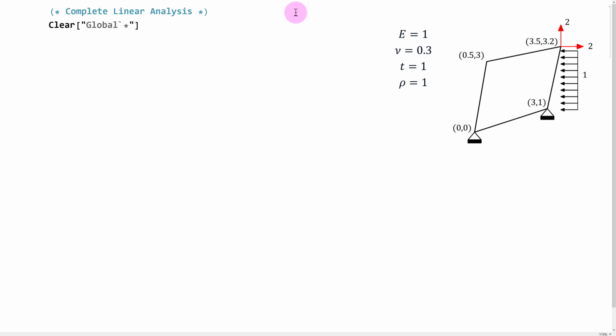If we look, we have our element geometry and our loading parameters, and we're going to figure out the nodal displacements of the element. In addition, we are going to use those nodal displacements to find things such as the stress, the strain, and the displacement inside of the element itself. This is something that often gets overlooked when we're teaching the class, in that once we find those nodal displacements, we usually say, all right, we're good to go.